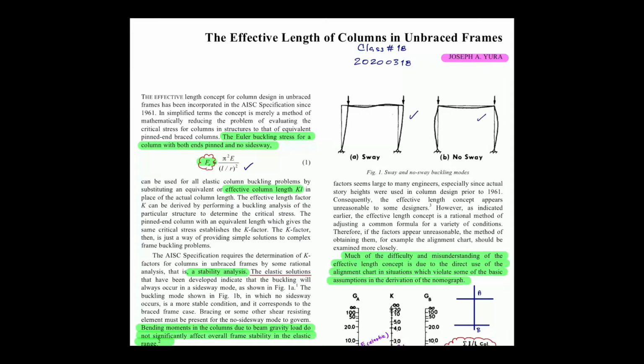So the point is that we are focusing on the effective length of column determination in here, and you know that the analysis which is possible and easy enough for us to do generally is the elastic analysis with the effects of the nonlinear geometry integrated in. So the geometric stiffness matrix is used in the analysis.